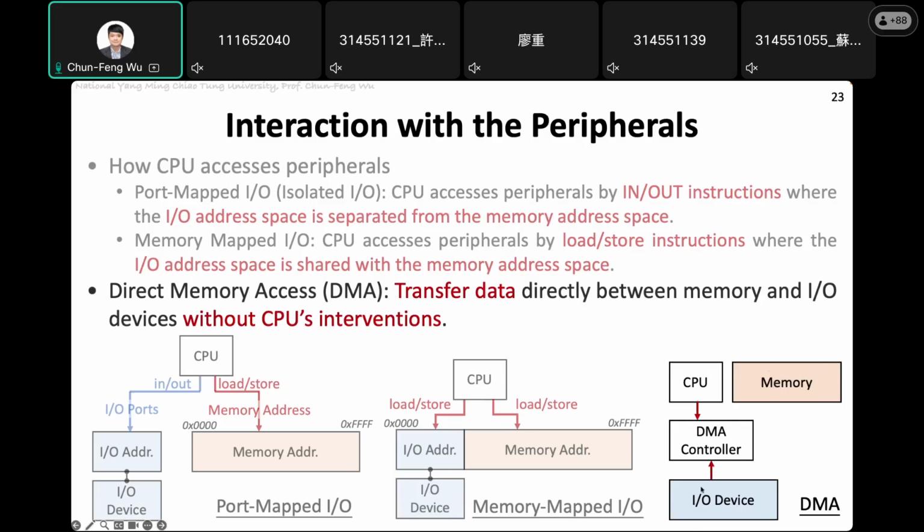The DMA will move it one by one, just like a watchdog, checking whether the memory addresses are correct. Then the CPU doesn't need to wait and can go back to do other stuff. This is the good thing about DMA: you spend a little extra overhead on this extra hardware device, and you relieve the overhead of the CPU.